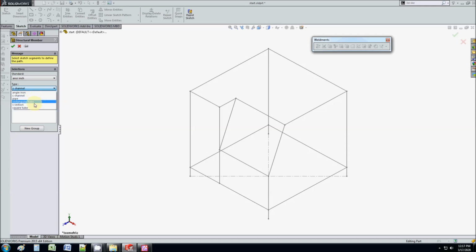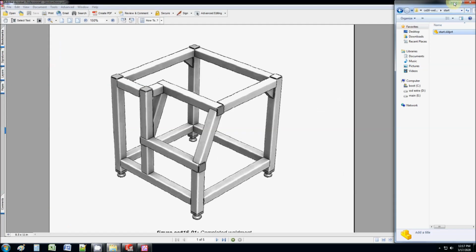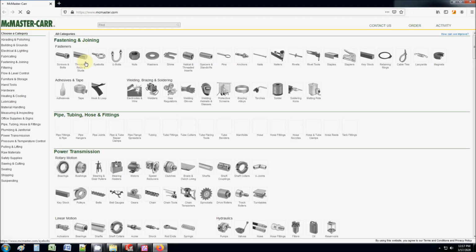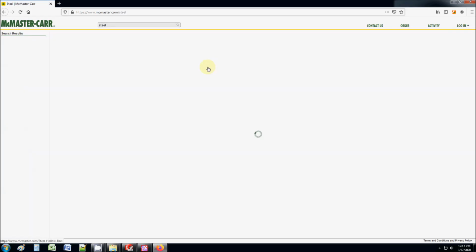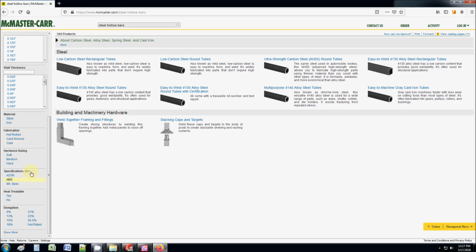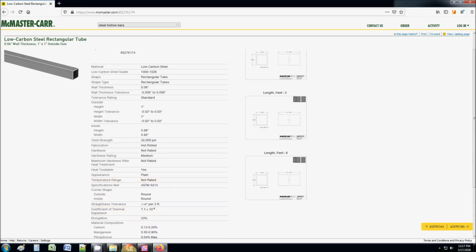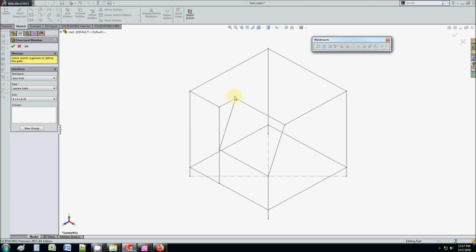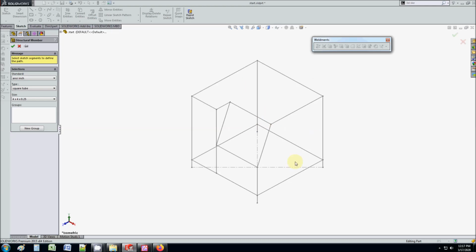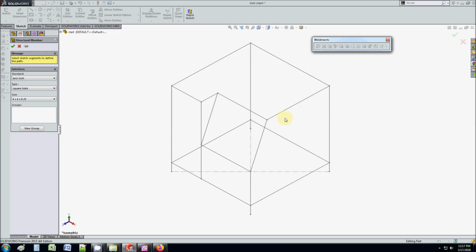So today we're just going to pick a square tube, and it's going to be a 4x4 by 0.25 width, length, and thickness. But one thing you got to understand is make sure that this structure exists in the industry. When you go to a supplier site, make sure that the structure exists, for the width, for the length, and all that stuff. And make sure it's abundant. You may even want to talk to the suppliers and see, hey, do you have this available? You don't want to spend all this time designing and realize that the structure doesn't exist, and then you got to start over and waste all that time. So make sure to do that verification before you start selecting the cross section.